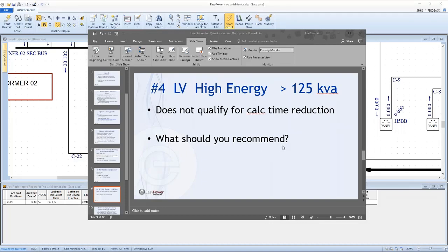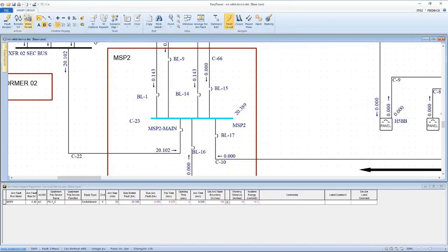Any reason to use the panel schedule instead of a bus with individual breakers? Brian's saying there's any reason to use the panel schedule instead of a bus with individual breakers. Apart from being able to generate panel schedules, the panel schedule object is kind of hard to step through and populate, but perhaps there are uses for the schedule apart from generating panel schedules and demand loads. Great question, and let me address this while we're going into this same topic.